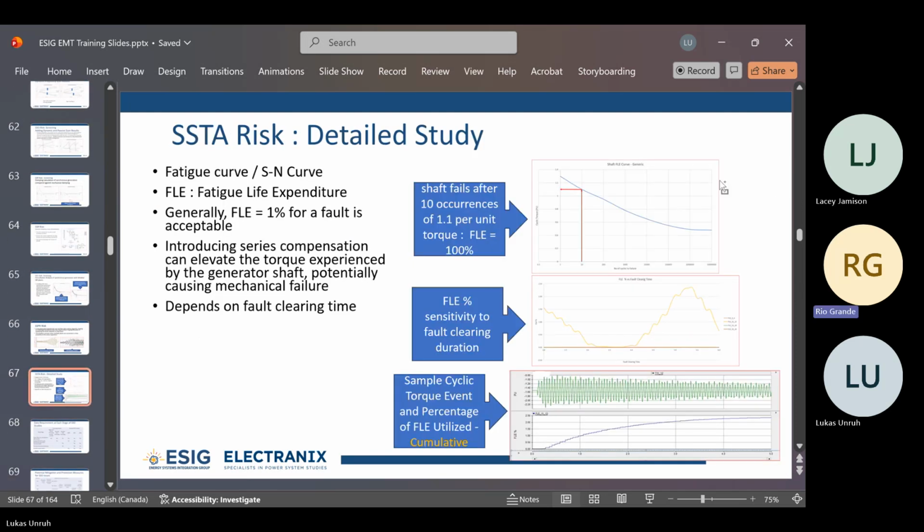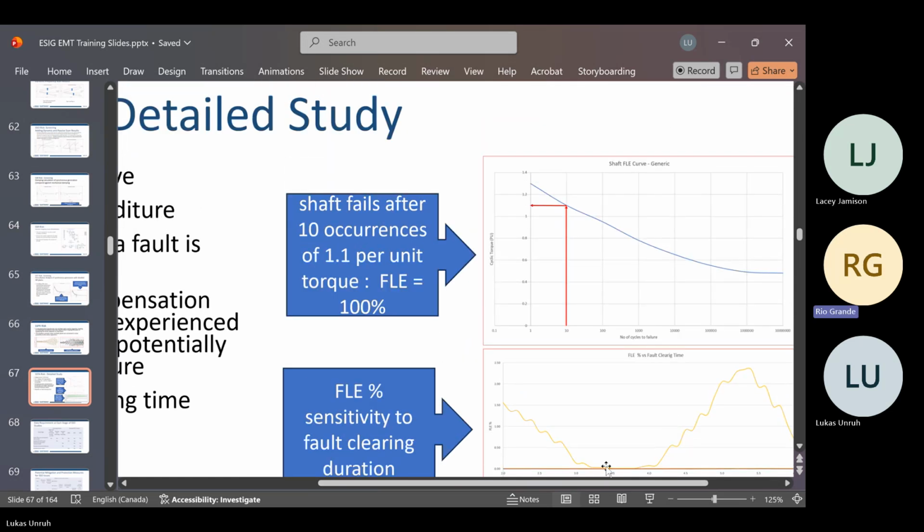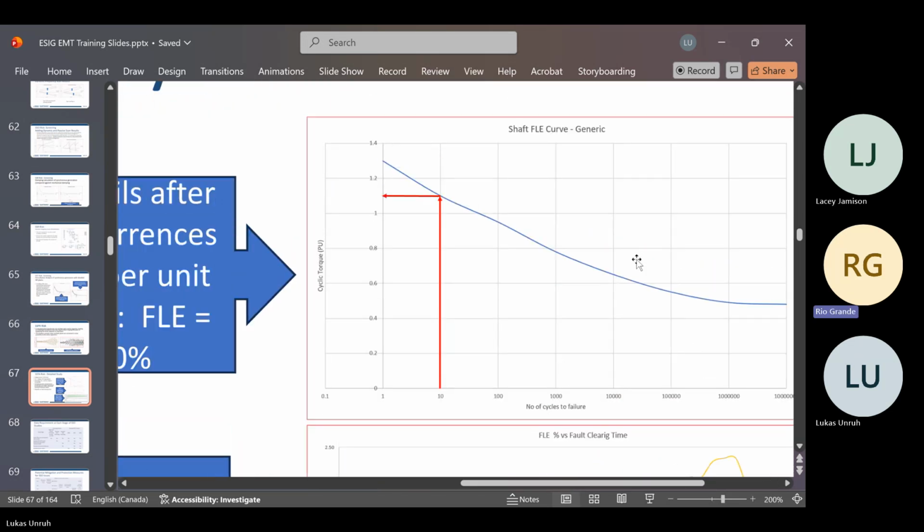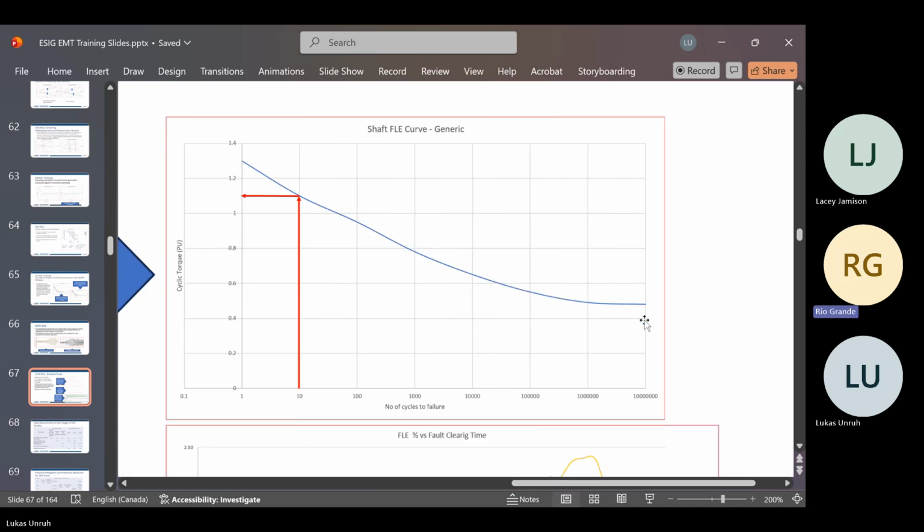So here is an example SN curve, and you can see that in this specific one there's some bottoming out of the curve, where it will saturate. Here we're at, I don't know, 1 million cycles or something, but keep in mind that these loads are doing this 24/7, and multiple times a second, right? So 1 million cycles is nothing. You can assume infinite cycles effectively from these load profiles. If they were doing something problematic, you might as well assume that it's infinite, because it's not event induced or something.